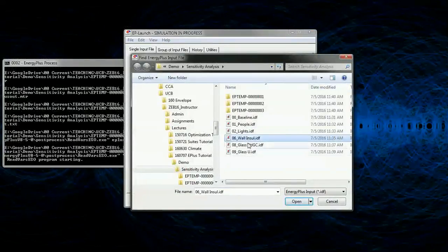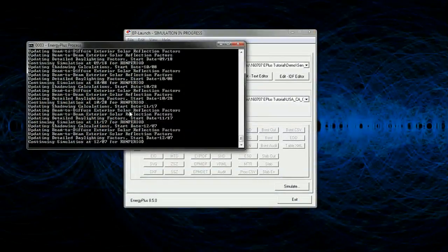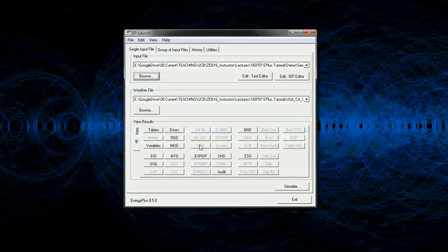Anyway, you can simulate all of these simultaneously just by clicking through, and this is a much faster way of running them all. And then make sure, however, when it gives you the dialog box, that you're checking the warnings for all of them, making sure that it's the same warnings and you understand them. There's no severe errors. In this case, there is.